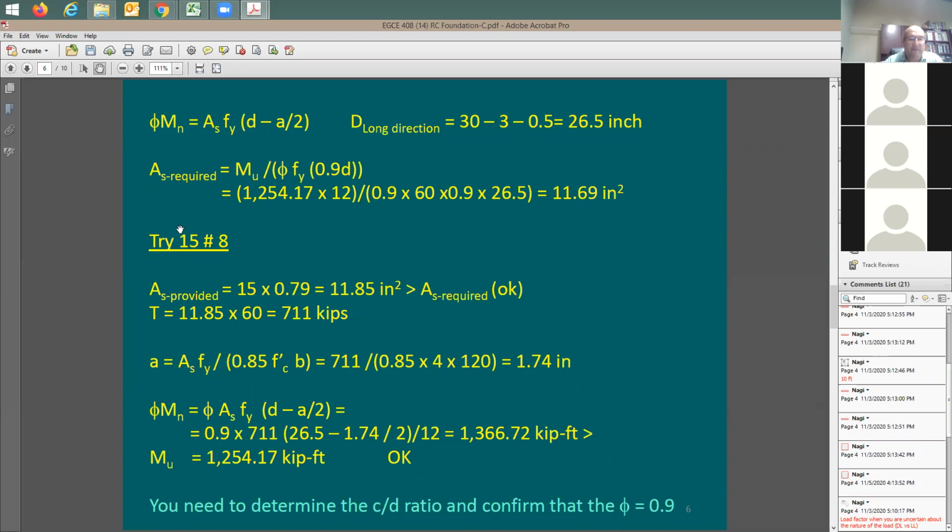In your midterm, I'm going to specify the rebar size that I want you to use. So you can say, for example, here's this many square inches of reinforcing that I need. So I'm going to try, let's say you're trying number 9. So you can say I can go with 12 number 9. Why? Because a number 9 has a cross-section area of 1 square inch. So 12 number 9 will cover this amount of reinforcement that you have in there.